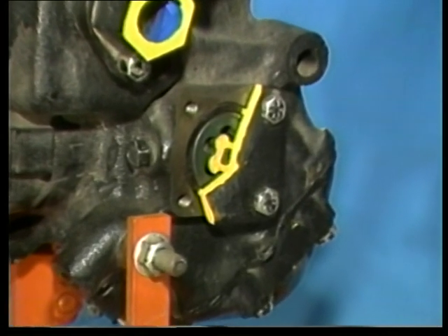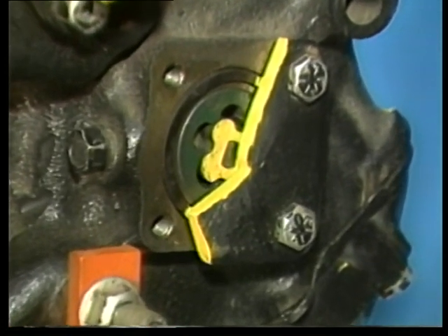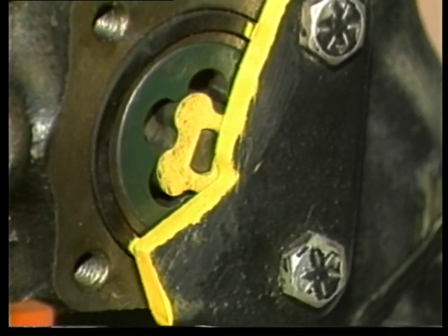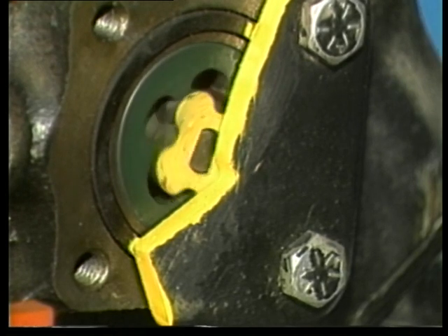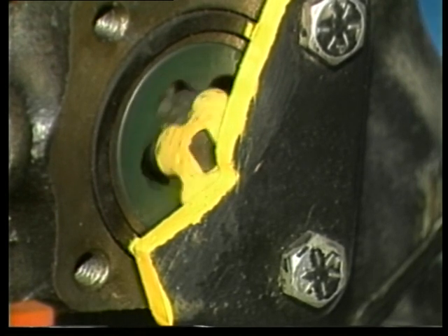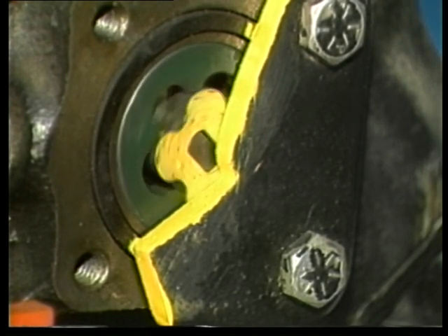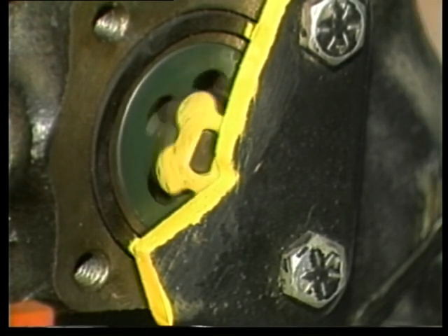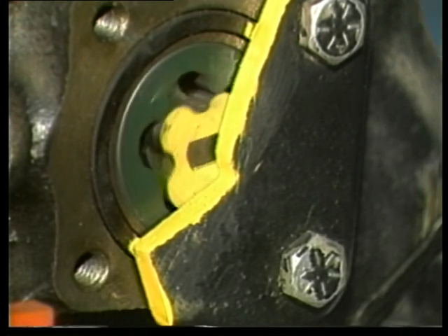Some compressors use an oil pump. A pump is used when the compressor is equipped with a sump or storage area for oil. The oil pump is rotated by the end of the engine crankshaft. This causes oil to be forced through the internal passages of the compressor to lubricate moving parts more efficiently.